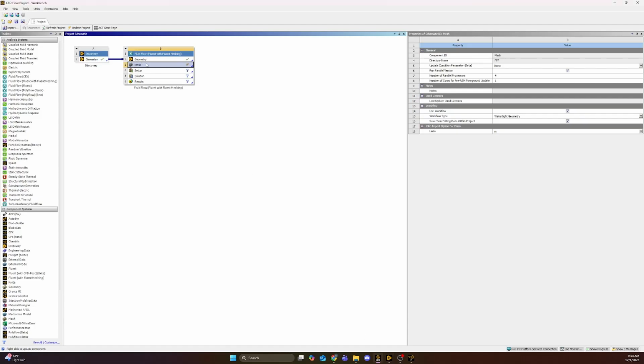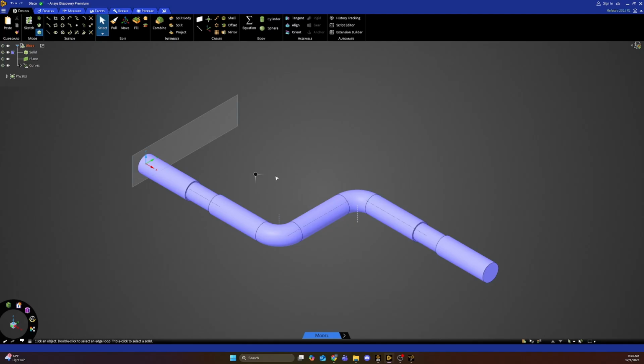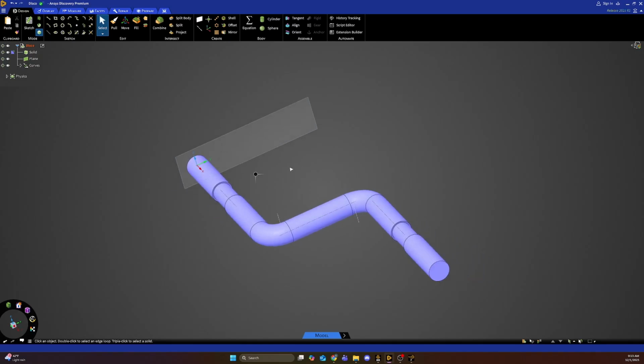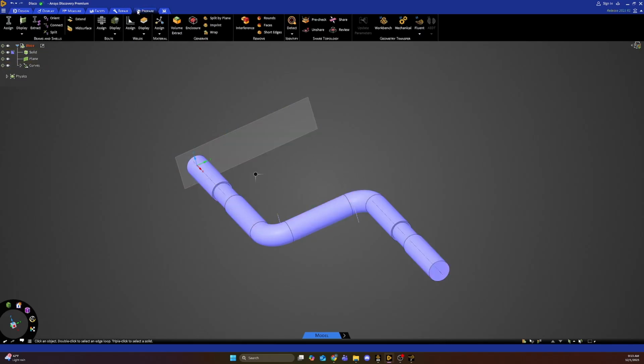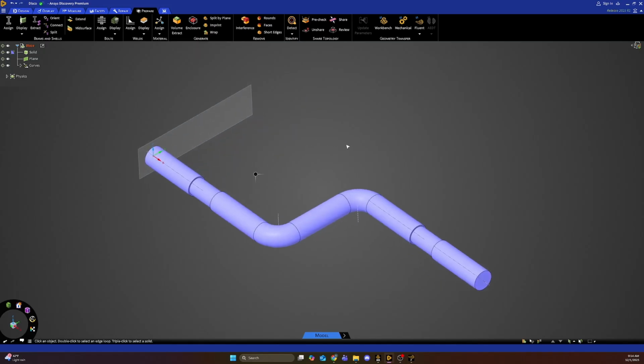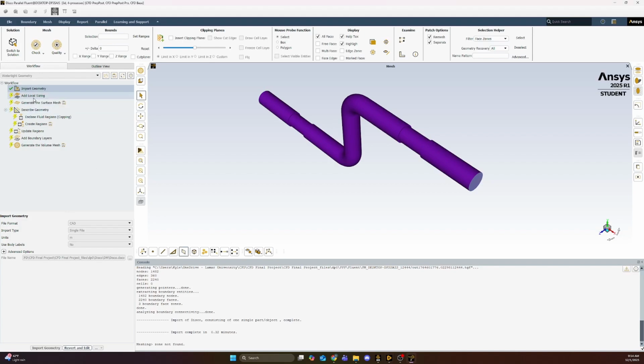And from there, I also wanted to mention this. If you have a piping system, like let's say you have it from SolidWorks or whatnot, and you want to pull the fluid domain as what's shown here, you can go to the prepare tab, and I think it's prepare. Yes, volume extract. You can use this tool. There's many good videos online that you can follow to use this tool effectively for a solid portion of a piping system if you want to extract the fluid domain to make it more computationally cheap to run.